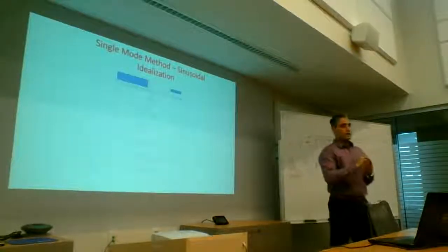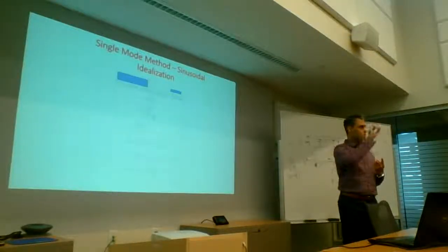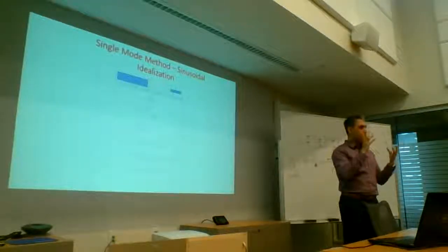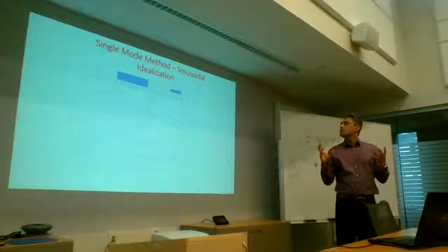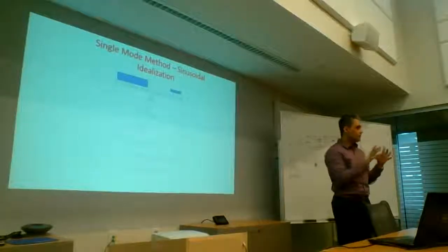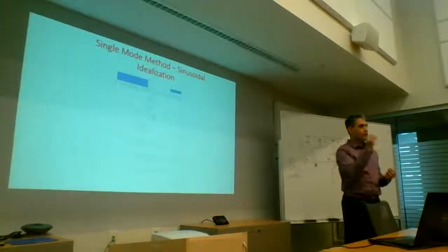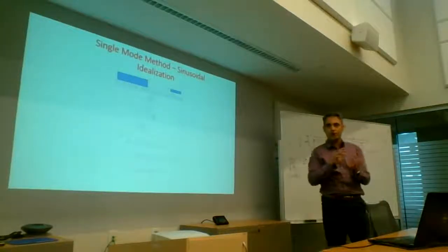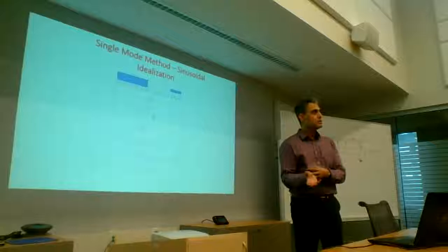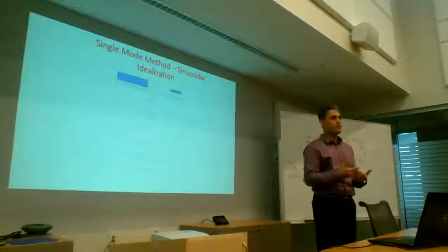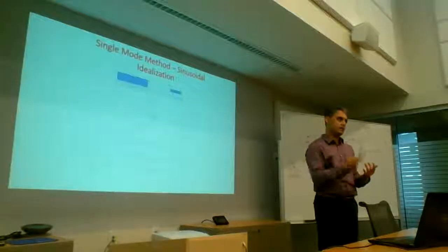Okay. Check very simply with the 12EI over L cubed or 3EI over L cubed what my period should be in that sort of range. It won't be exact, but if you end up within 10-15% of what the software is giving you, then you know that you're close enough, right? You haven't missed a fundamental thing in terms of stiffness and mass. Those are the two things.